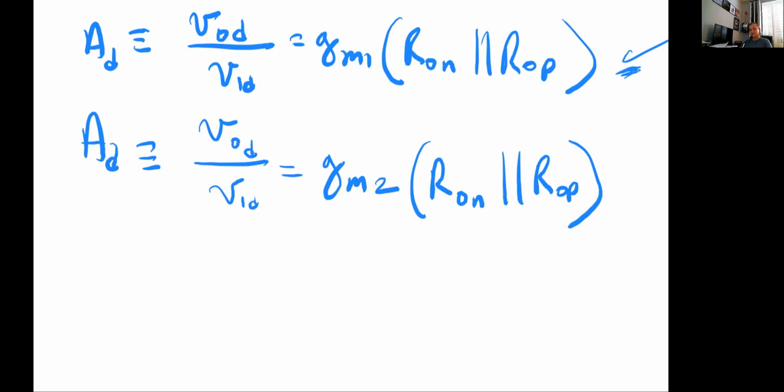And my differential pair amplifier is supposed to be amplifying differences. So if the common mode voltage changes, that should not affect the output at all. But in reality, that doesn't happen. There is some fluctuation. And how immune my differential amplifier can be to variations in the common mode voltage is what we call a very important metric for an op-amp, which is the common mode rejection.